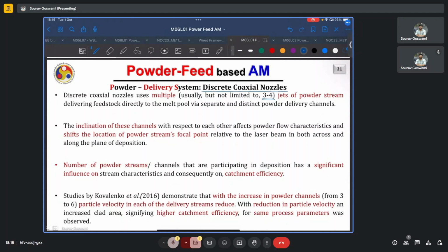You are also able to better control and actuate the composition of the powders. If you want to build functionally graded materials, or develop new alloys for additive manufacturing, you want to alloy powders on the fly, rather than pre-mixing them via some process such as ball milling or planetary energy milling.